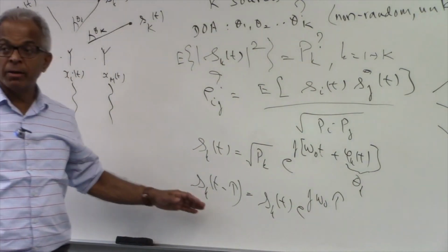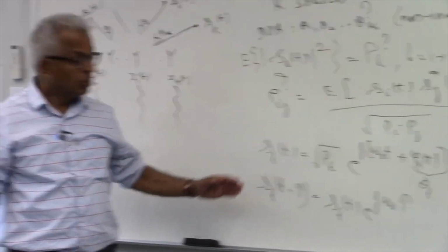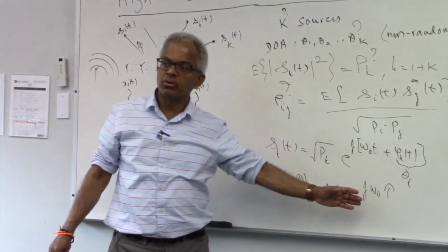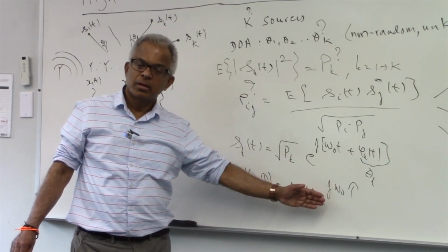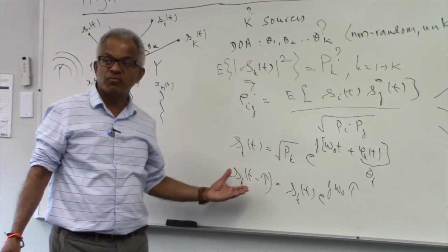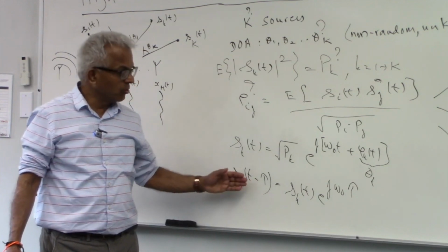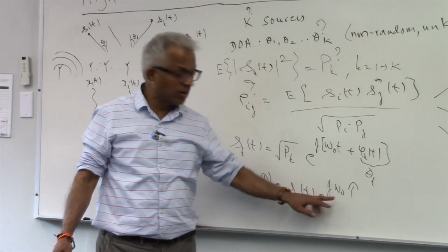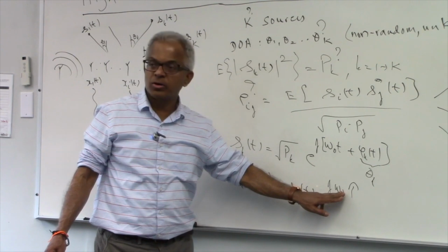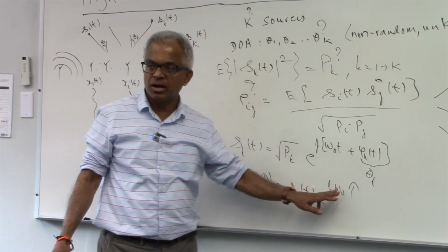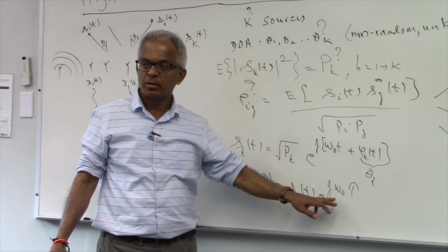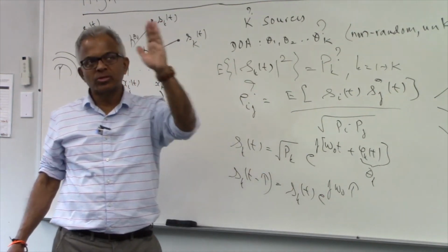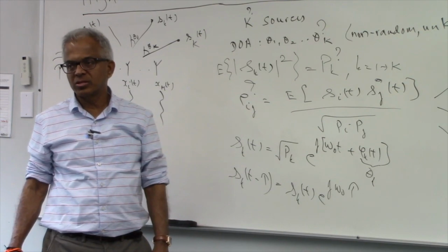If it is wideband, a delay is a delay. So if we want to bring this delay in as a phase delay in the wideband case, you have to take the Fourier transform. When you do the Fourier transform, it is true you do get a similar relation, but it won't be omega naught here. It will be a general frequency. Whatever the frequency is here, that will be frequency omega. That means you then have to go to the frequency domain and look at specific frequencies and so on.